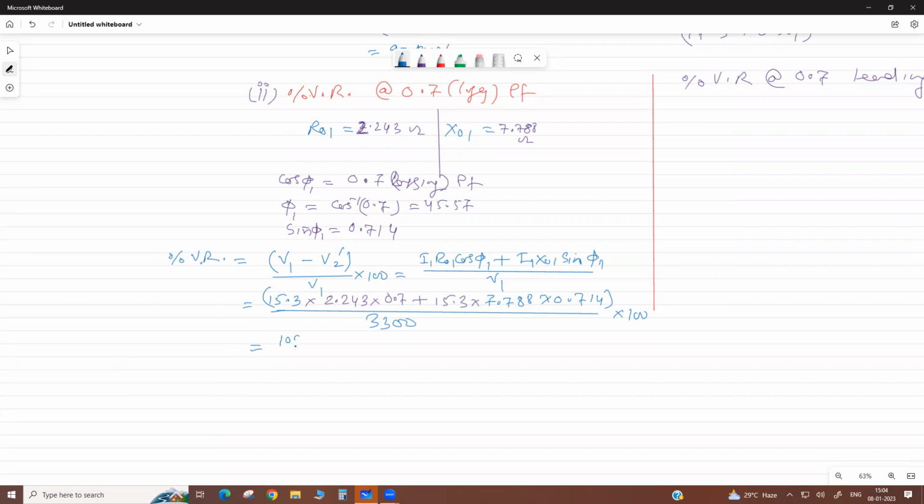The total comes to 109.117. Divide by 3300 into 100, and the percentage voltage regulation comes to 3.36%. Okay, dear.